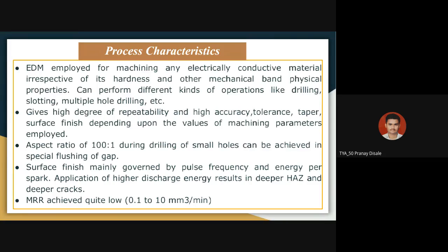Then by changing your dielectric fluid also, that means if you use mineral oil or deionized water, what will happen? That also you can see. Or you can check by changing the flushing method also. What will happen to the performance? That also you can check.